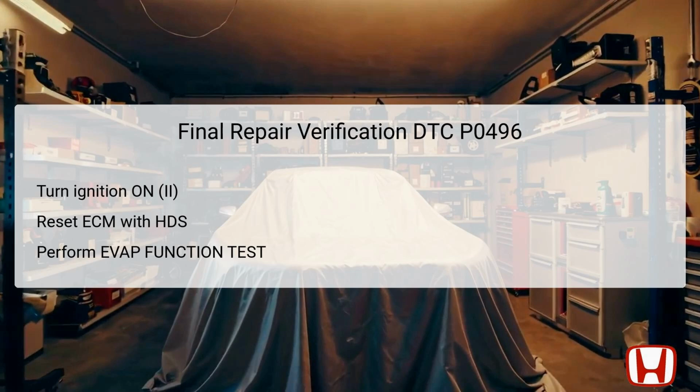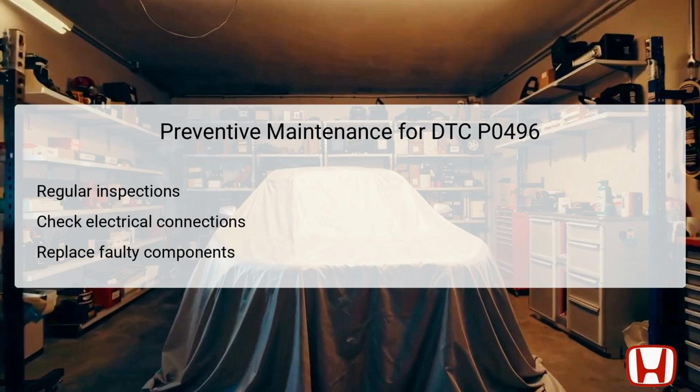After resetting the ECM, it is essential to perform the EVAP function test once more to check whether the system is functioning correctly. Verify that no new or recurring codes show up in the system diagnostics. If the DTC P0496 does not return and the test is successful, your work is complete, reaffirming that the repairs made were effective.